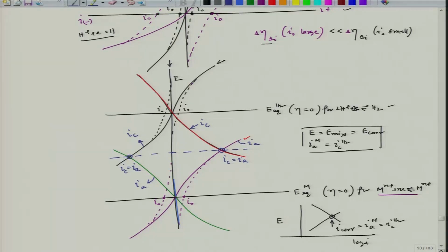So, it is basically, since the green one is the mirror image of this line, and this is the mixed potential. So, this potential becomes E corr. Now, this is the plot that we get, and if I take a small overflow, that means this will be the steady state potential we will reach, where the rate of cathodic reaction equals the rate of anodic reaction.